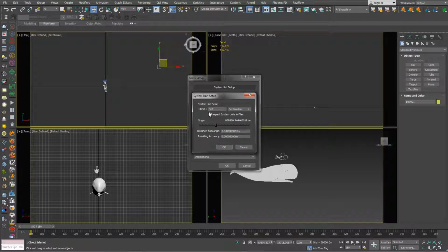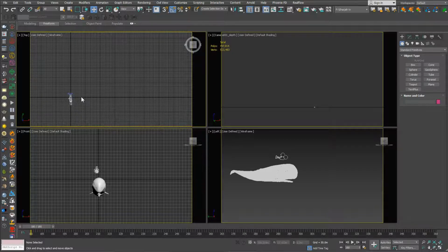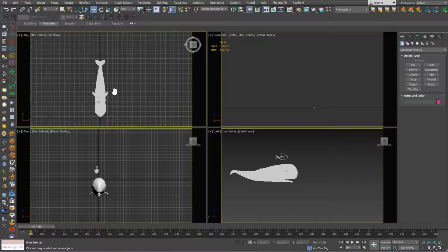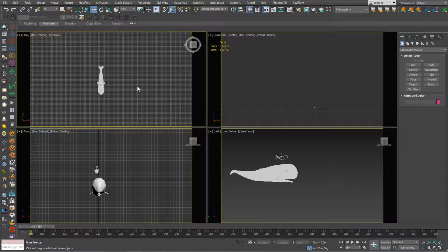So 3ds Max will pop up this mismatch message and ask you to make sure that the units in the opened scene are the ones considered, not the units in the previous scene. So all you need to do is keep everything as it is here and start working. Make sure your object is as close as possible to the center, to the origin, as we have here. It's not far away from the origin. Now we can start working on creating our container and bringing everything to work.